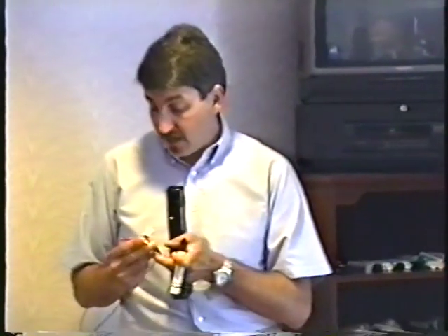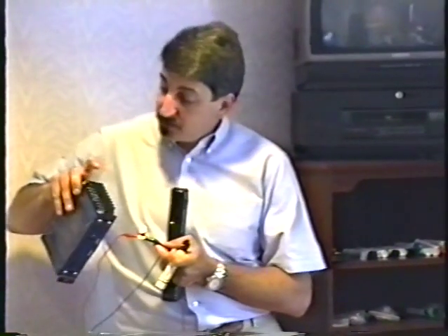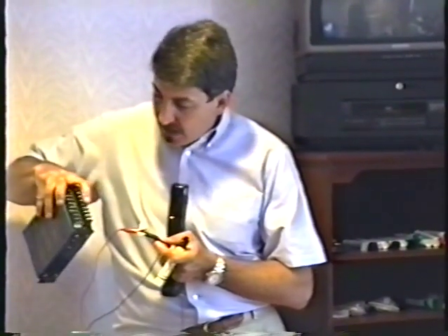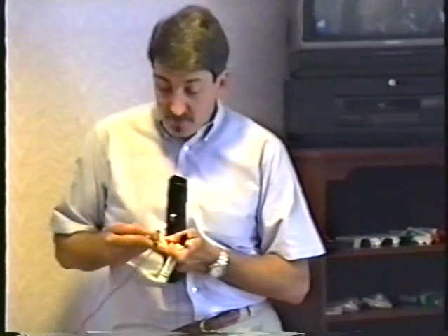And we'll see later on when we take a look at conversion kits and how to hook up games, to carry the 5 volts from the power supply to the logic board, you want to use several wires. You want to use 3 or 4 wires, because they'll have less resistance that way, and it will enable the electric current to flow much more easily.